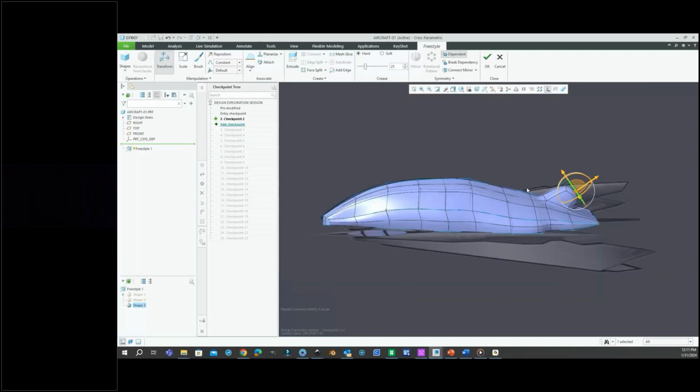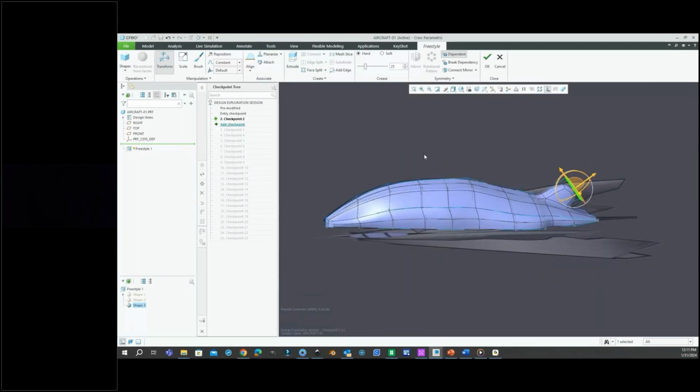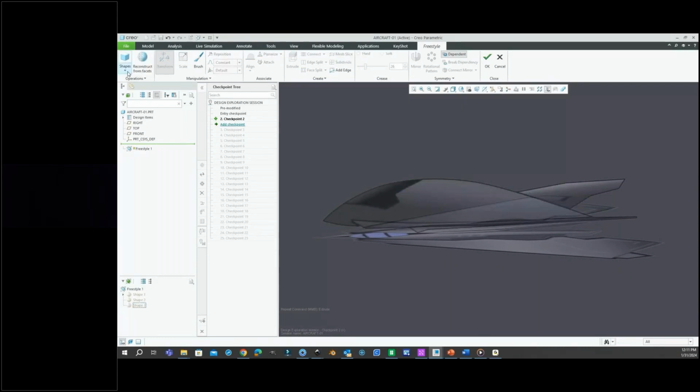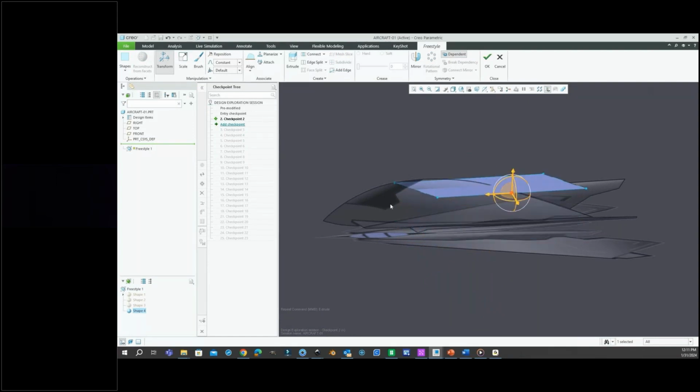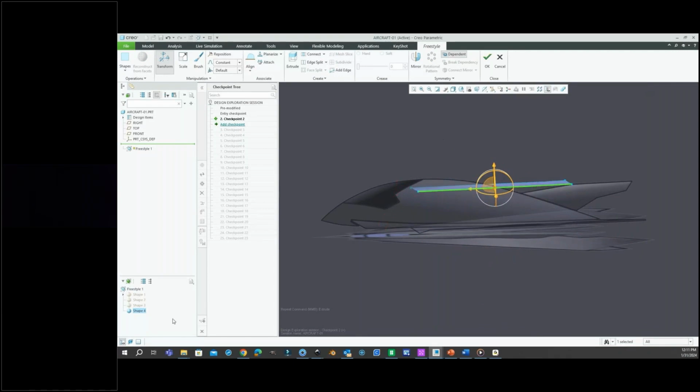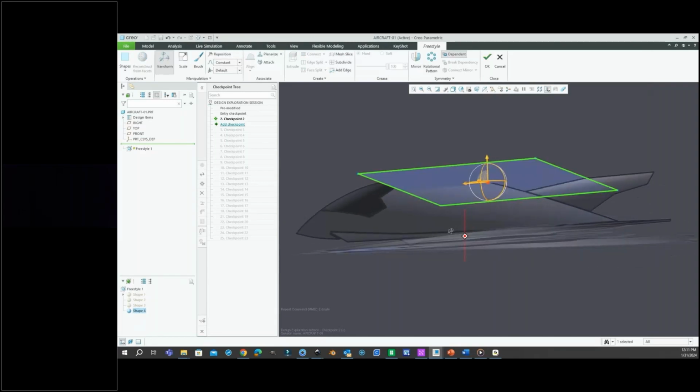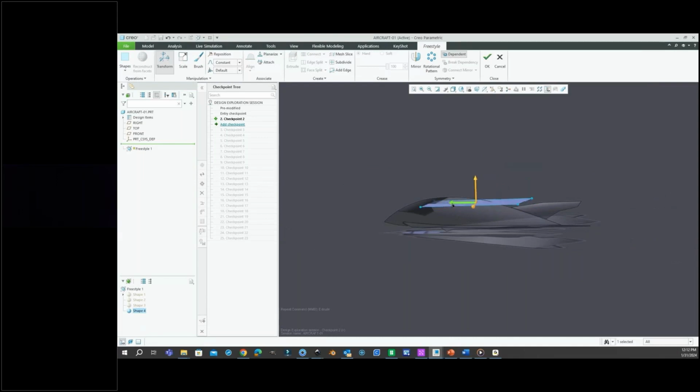Okay. So we saw this, starting with a sphere. We saw box mode here with a cube. And there's also starting off with a plane. I can use a plane as well, rotate that plane, drag it up to where I want to get started. And if you want to select the whole mesh, an easy way to do that is either box selecting here or just grab the shape in the freestyle tree. Move these over.